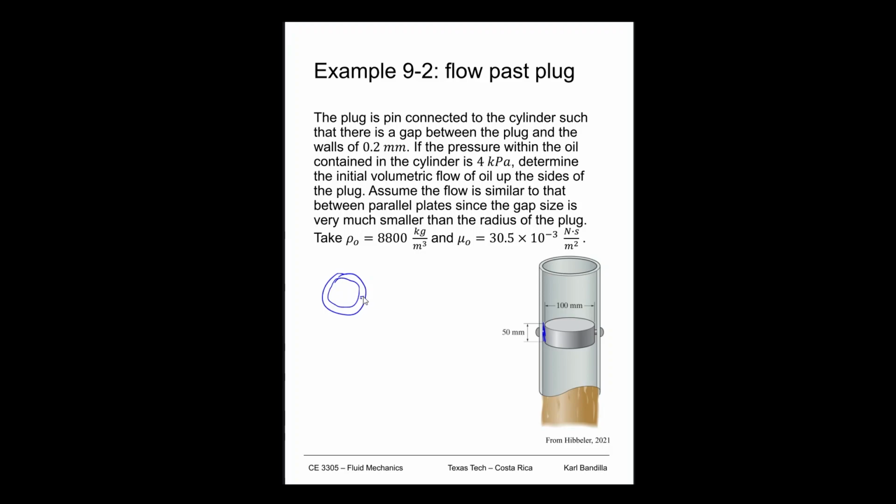Where the oil is going to be coming through this kind of a ring here, right? But we're told to take this and unravel it, make it two separate planes, right? So we can cut it somewhere like this, and we're going to have instead an opening that looks like this, which basically gives us two planes, right? Of course, they're not going to be closed on each end because they're touching each other there. But we're saying that the height is so small compared to everything else that it's going to feel like we have these two parallel plates.